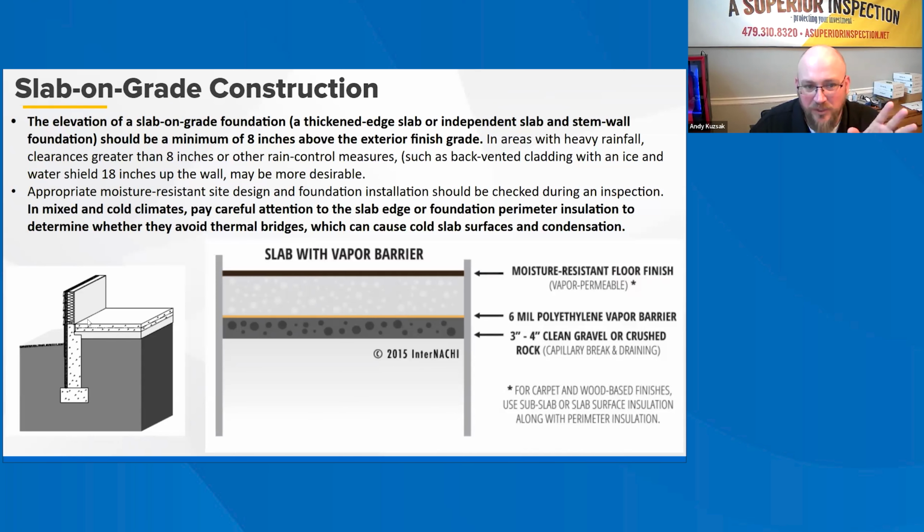So just keep an eye out that when you're doing your inspection, if you see where the wood is darker, and especially if there's not a window up above it or a door near it, and the wood flooring is darker on the perimeter, oftentimes I would use my moisture meter and check that area. And if you get elevated moisture levels, I would call that out to the client and recommend them to, if it's rotted, it's a problem. There's going to be a great picture of this at the end of the presentation that will explain this a lot clearer. But definitely call that out in your report if you see that and recommend it for monitor or further investigation.